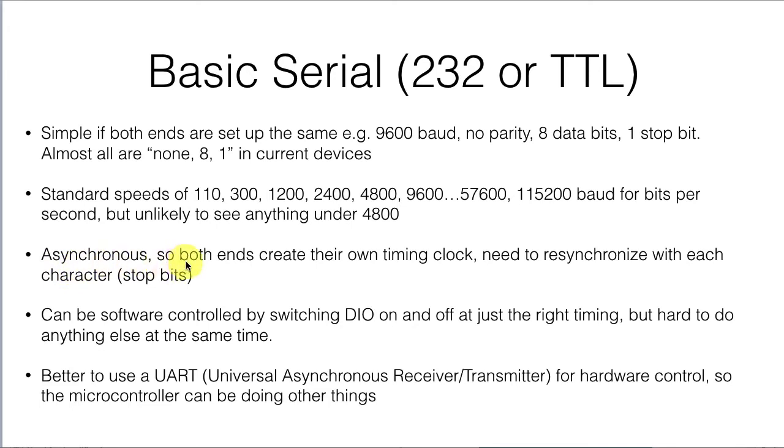It's asynchronous. What that means is that both ends create their own timing clock, and they don't have any need to resynchronize with each other on those clocks, but they need to resynchronize every time they start receiving or sending a character to line up with each other. So these stop bits in the protocol take some added time.